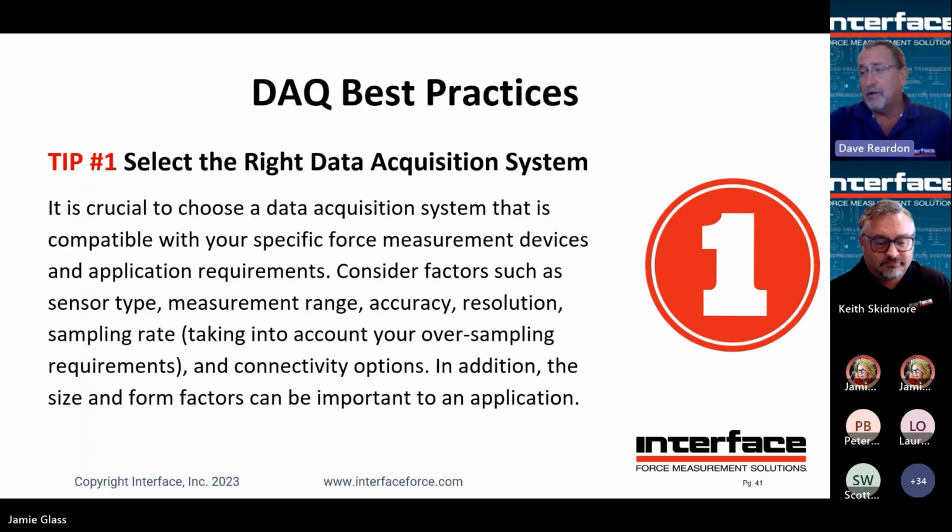For example, if the frequency of interest is 1,000 hertz, you taking Nyquist into account, you probably want to be recording at some factor above that, whatever your requirements are. For many people, the standard used to be 5 times oversampling, but that slowly has changed to make it so that 2 or 3.5 times oversampling is good enough. I know that there are some applications where you have to do 10 times oversampling, where the data is very fast.